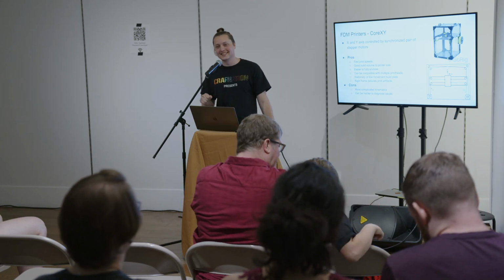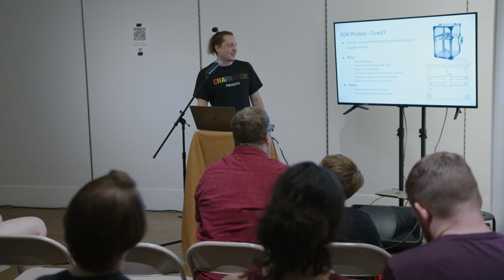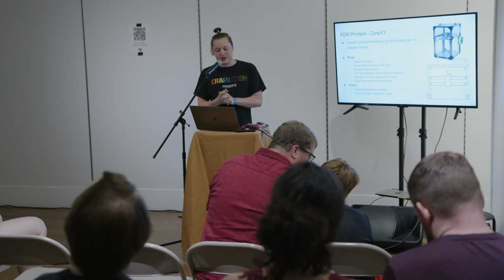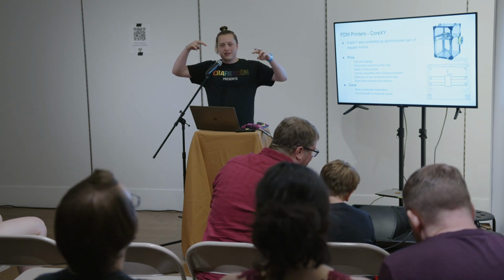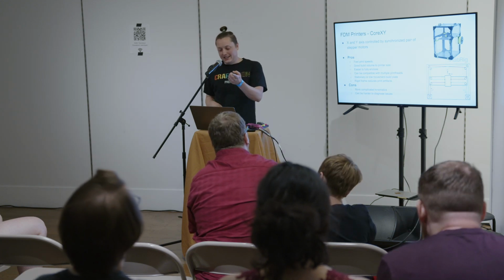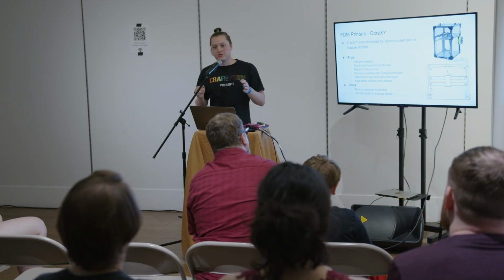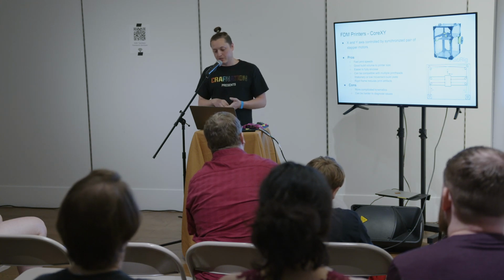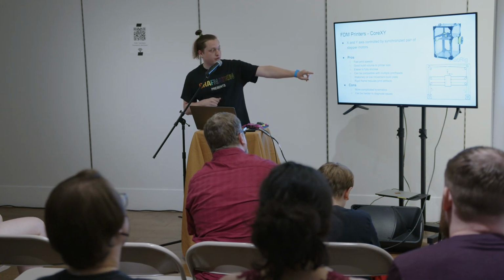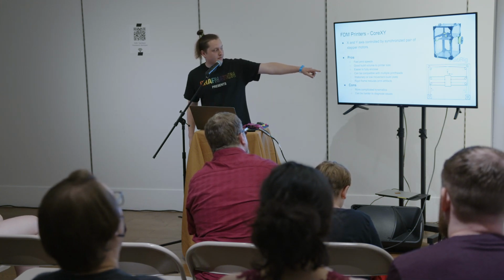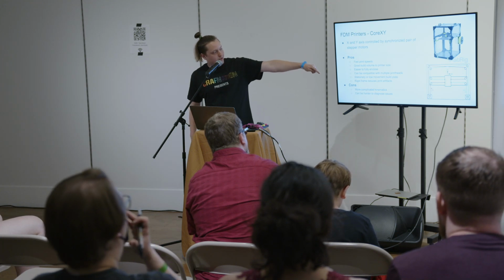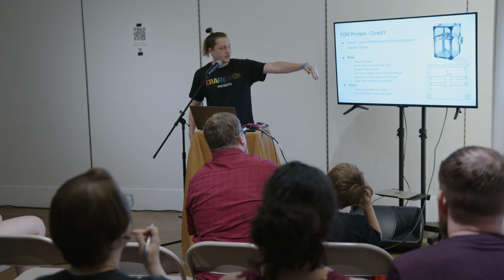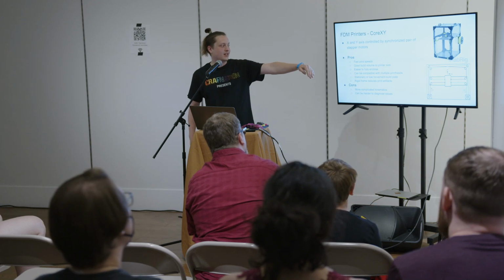The cons are, it has a very complicated printing mechanism, where for it to actually move directly in the Y, you have to move both stepper motors at the same time. If you were to move just one stepper motor, say the lower right corner, if you were to pull, it would move diagonally down to the right, and vice versa.